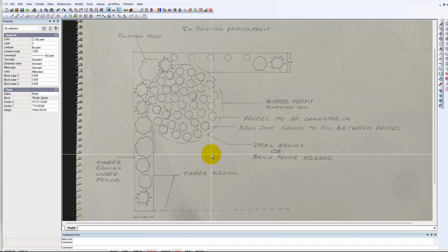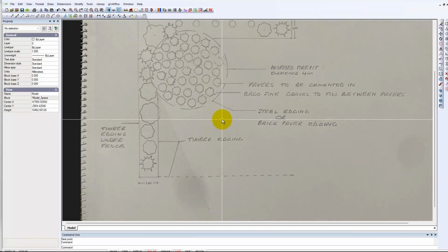And what we're interested now in doing is adjusting the scaling factor of the hand sketch. So I use the distance tool. I put polar tracking on, and I scaled, and now I can measure across and I get very close to a meter. A meter, being we work in millimeters, so we wanted that distance to read 1000 millimeters, and it does. So now the current drawing properties are set in this properties box.